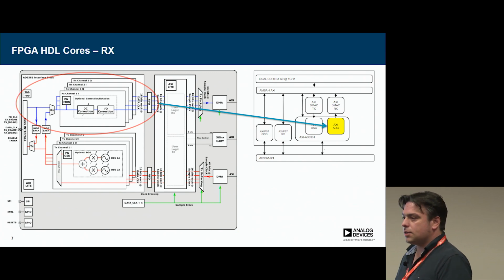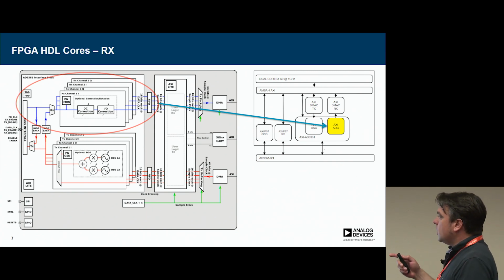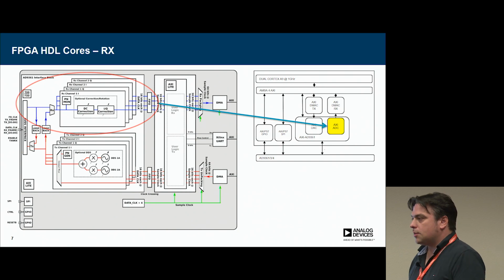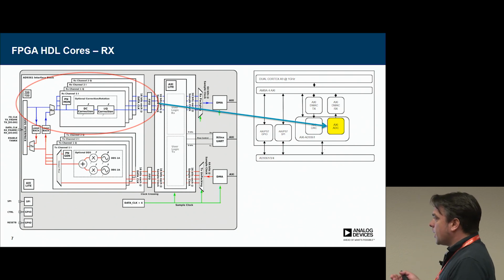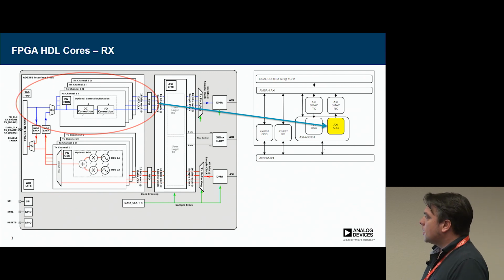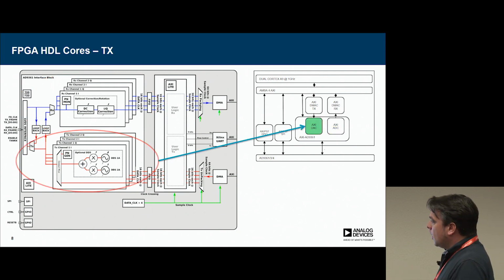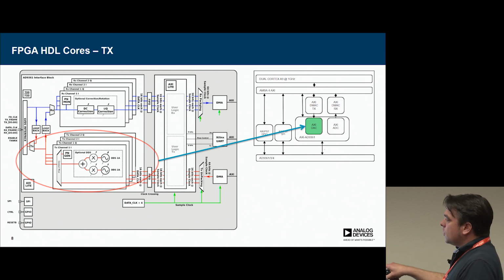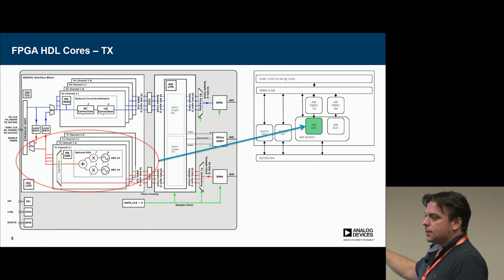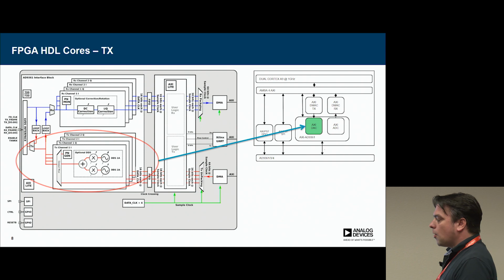So that's a block diagram of the interface core in the FPGA that I just introduced. It's also split into RX and TX. On the RX side, we have some matrix multiplies in there that allow you to do some IQ correction, even if it's not necessary with this transceiver, but you can still use it to do a phase rotation. Then there are some pseudo-random number checkers. On the transmit side, there are also pseudo-random number generators that allow you to do a loopback over the radio and back and see if the digital link runs without errors at speed.